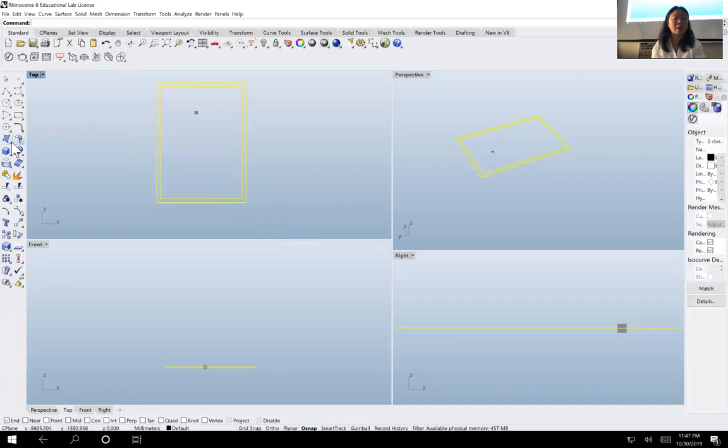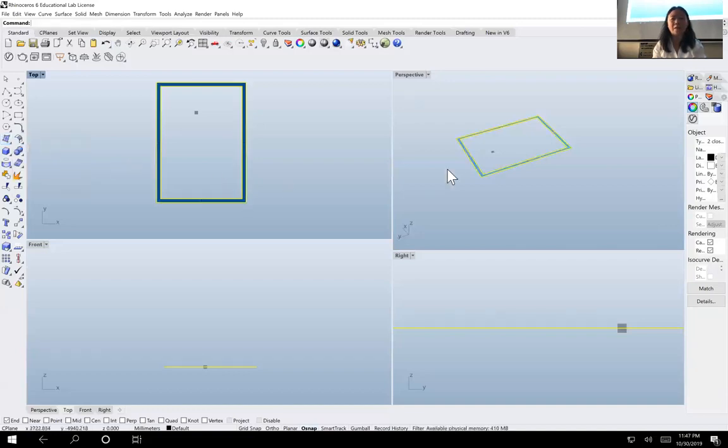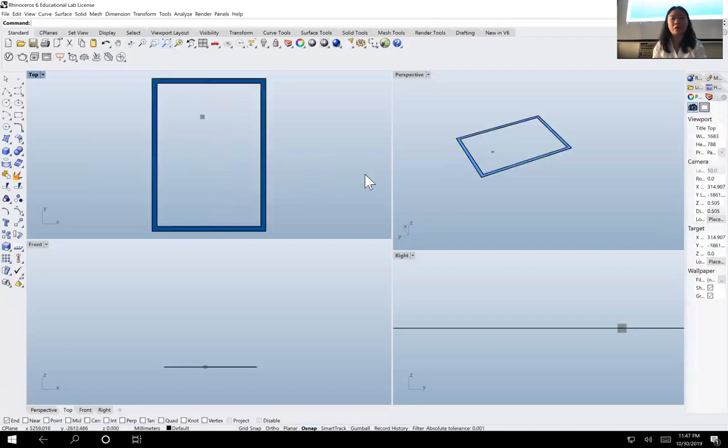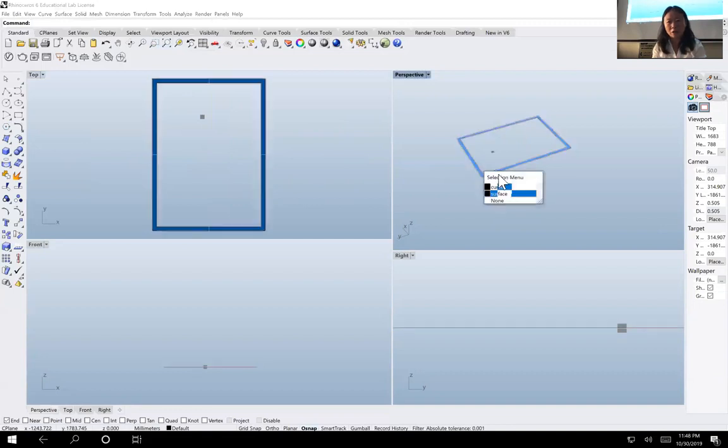With the toolbar, I'm going to here, this toolbar, the second of it. You do have to sort of remember where they are. This one is called planar. When I click on it, you will see there's a surface generated for you in between. Here is a surface, right? This blue thing is a surface. Before, it was only two lines. By the way, this blue you will not see because this is my setting. I purposely set it for demonstration, so the lines are thicker and there are colors so that you can see better. Now I have a little surface here. I still have those two lines.